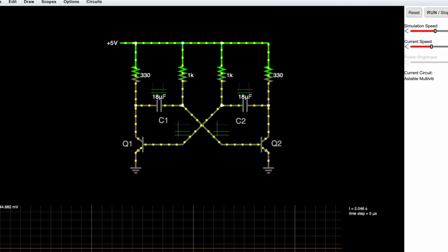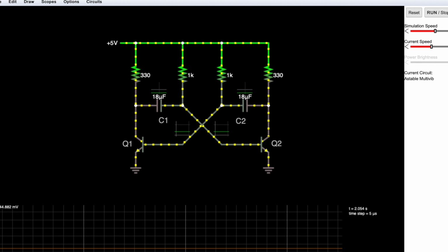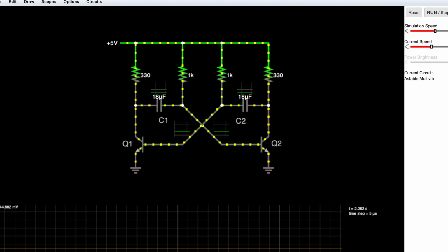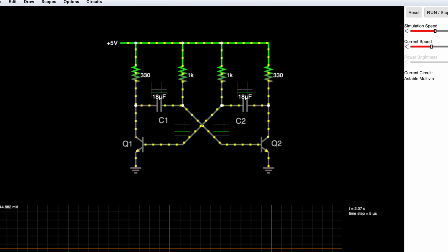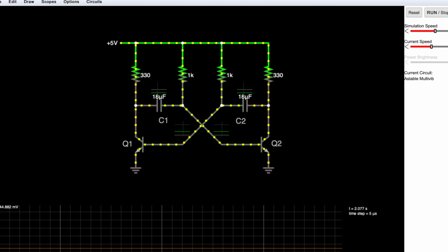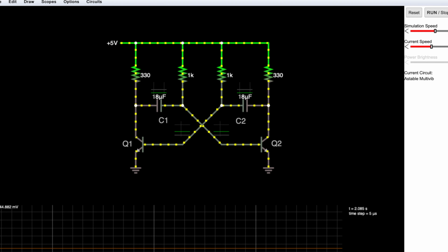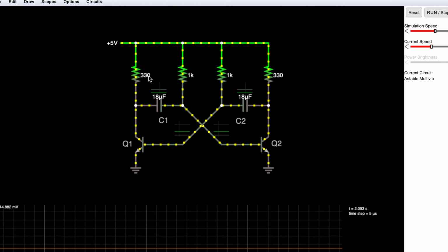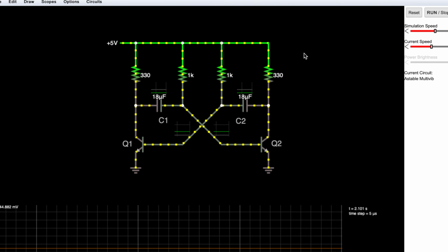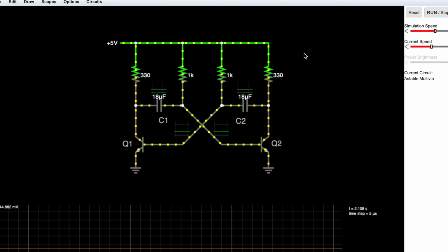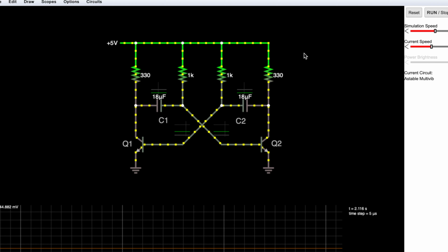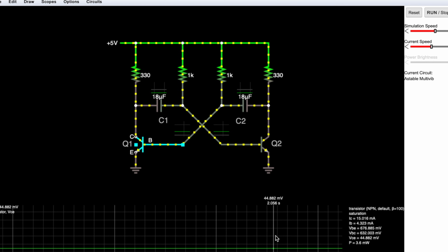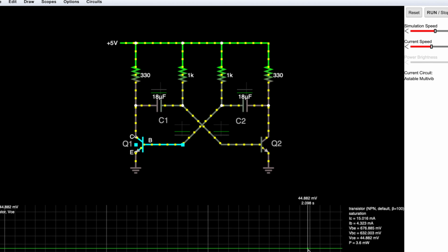Before we can simulate our circuit, I just wanted to show you something which I have mentioned in the past. It works in practice. Does it work in theory? And this is an example of it. In this circuit, if you notice, the left and the right are very symmetrical. Because the simulator is using an idealistic idea of how an ideal component should work, you can see that there are absolutely no oscillations. It's not oscillating at all.